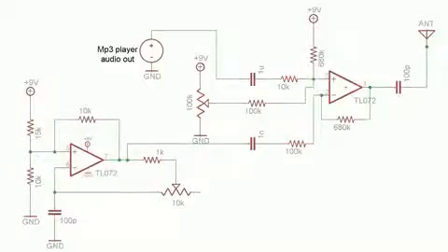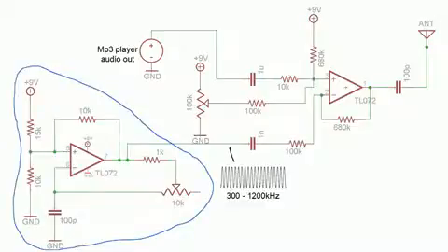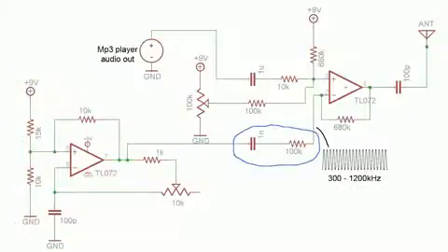So let's take a look at a circuit that can do this. The first half is the oscillator that you've already seen. It generates the carrier wave, which is a continuous high-frequency sinusoid. Over here we have a high-pass filter to remove the DC offset from the oscillator's output. The high resistance of 100K also helps to isolate the oscillator from the modulator, so that the modulator doesn't mess up the generation of a frequency-stable carrier wave.